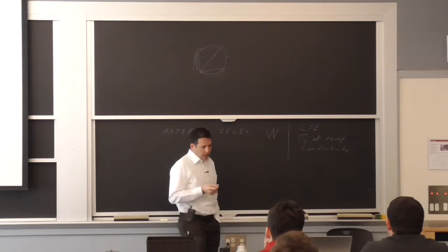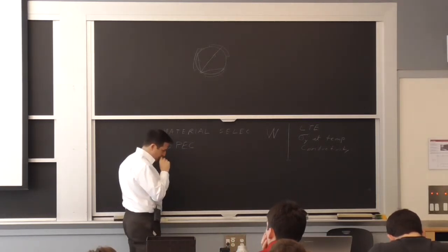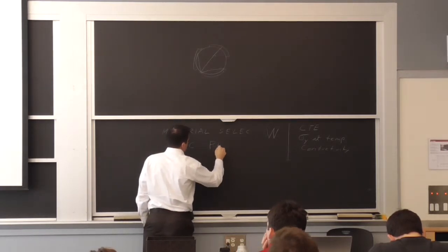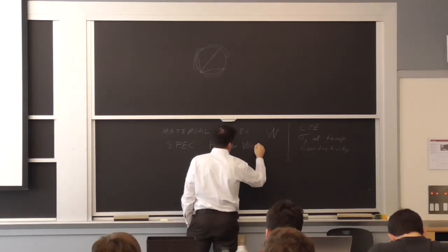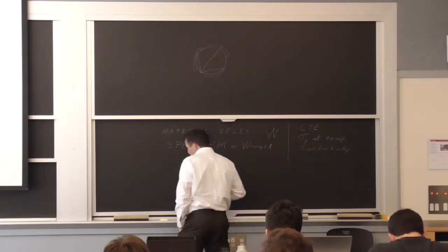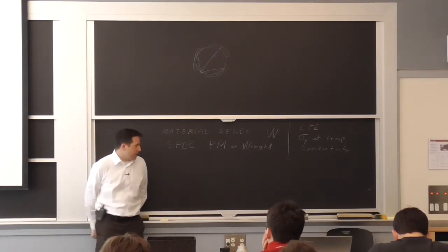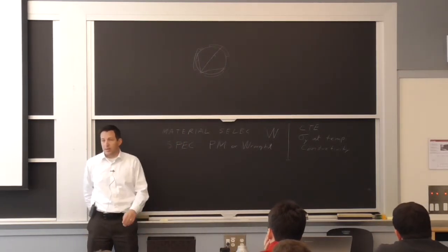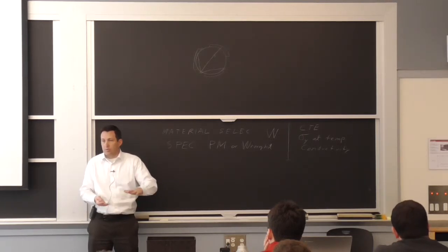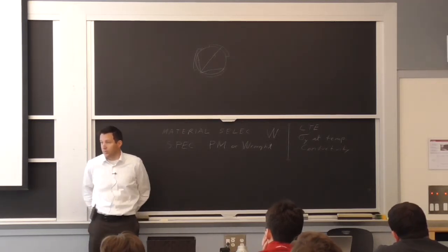in various quantities. Now, the second thing we talked about is the spec. Specification was, in this case, powder metallurgy, or just really a wrought product. And they didn't know which one was the best, and they didn't really understand all the differences. What it means to be a wrought product here, it means that the tungsten alloy was cast and then deformed. So if you start with a billet and you deform it, you roll it until you reach the thickness that you're interested in, and then you make a cutout, you got your disc, you're ready for production.